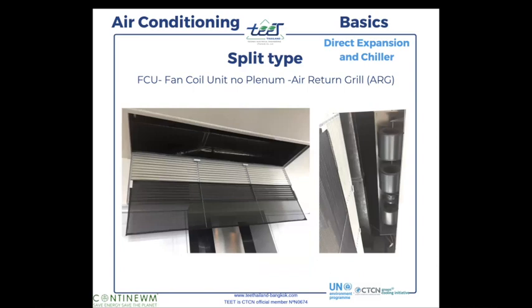Sometimes, like in this case, there is no plenum, there is no filter box, okay? So we have to do with what we have, and we have to install at the air return here. So it's not the ideal case because we are far away from the coil. So it will reduce the performance a little bit. It's not ideal because you have to install many more nets than if you have the plenum and the filter box. So the cost for the client will be higher and the ROI will be a little bit bigger as well, okay?